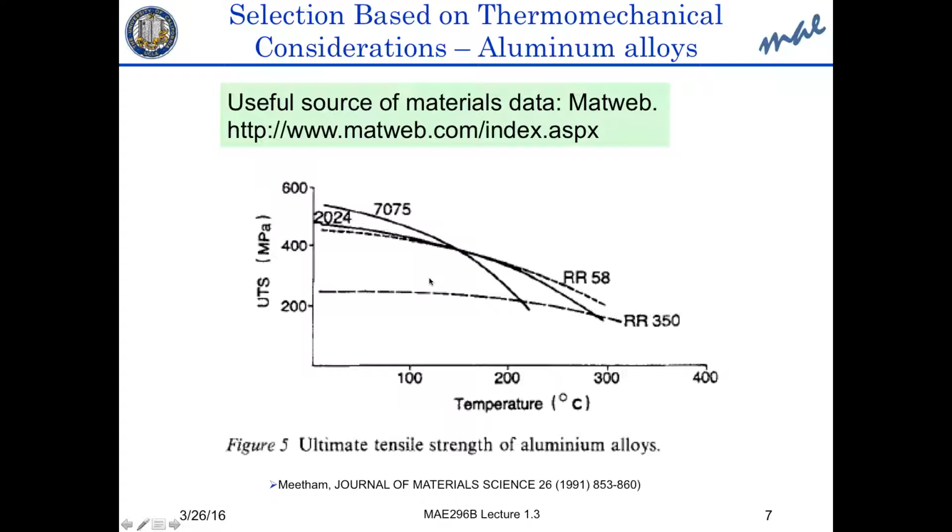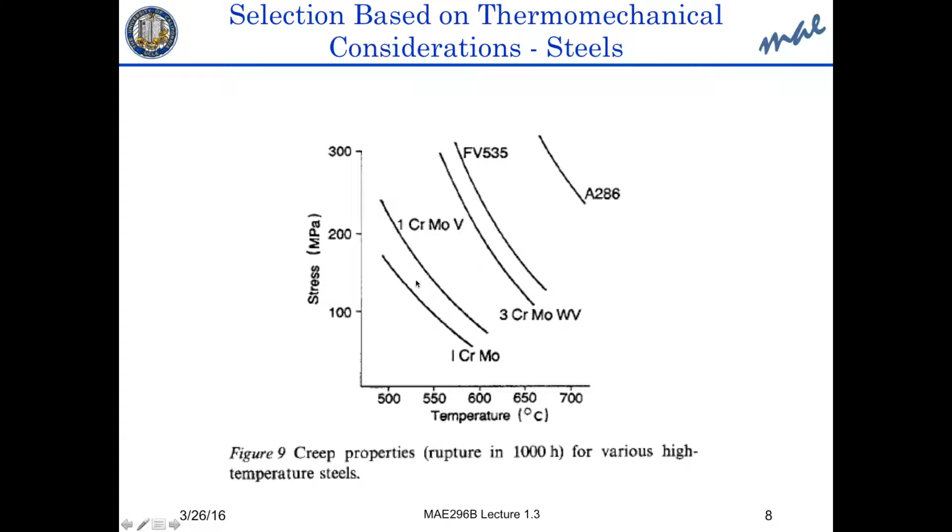So next, we will have to consider now steels, and steels are used in power plants, and these are called alloy steels. Alloy steels that must have chromium for oxidation protection, molybdenum, vanadium, and tungsten. They form carbides, and the carbides stabilize the steels at very high temperatures.